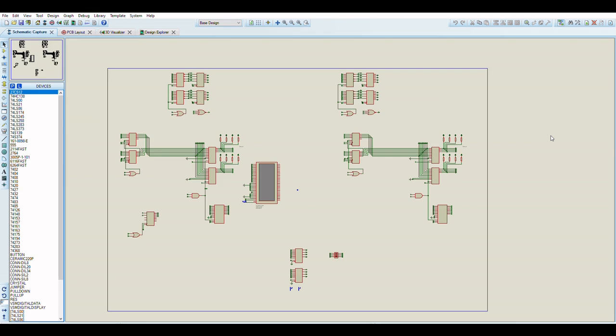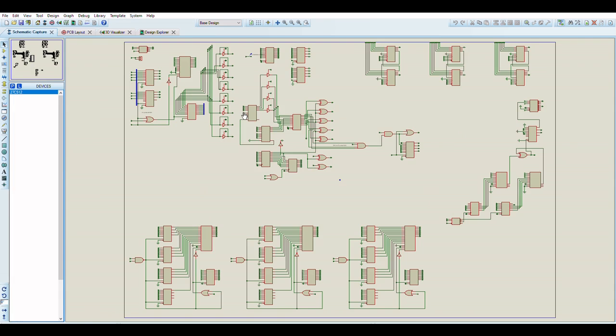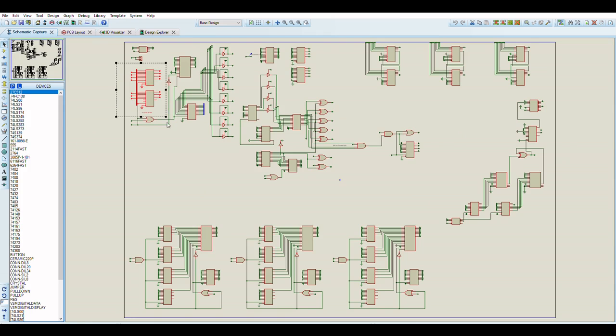Anyway, so I probably won't. Version 4 of the hardware, I might look at making it horizontally wider in terms of pixel size, and maybe even more pixels vertically as well. It did mean that, for example, the Sprite RAM registers, which are here on page 4, needed an extra binary digit for the high byte for the 9 bits worth of data for the horizontal sprite position.